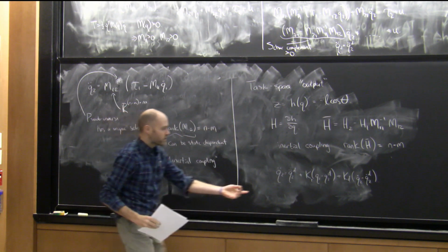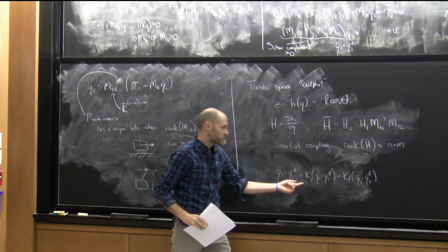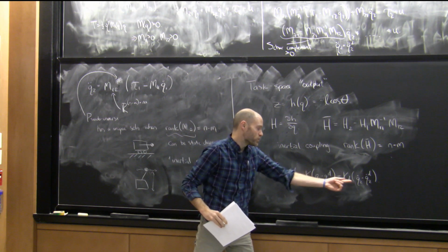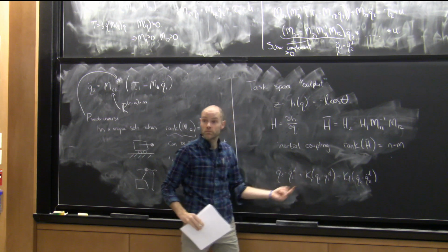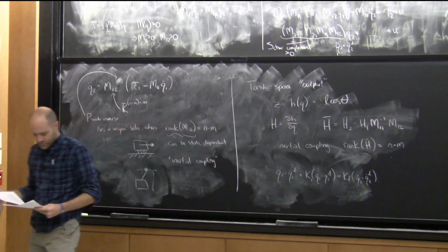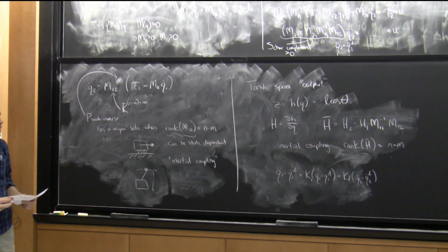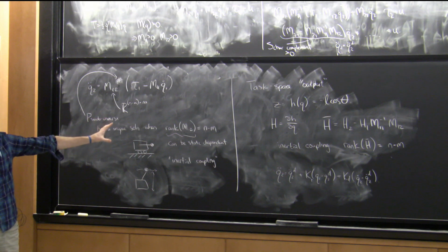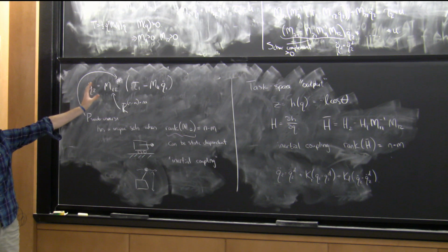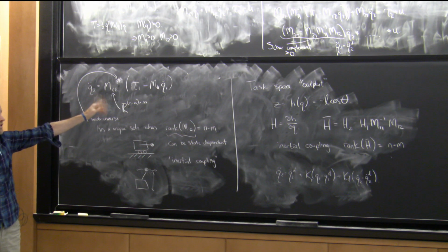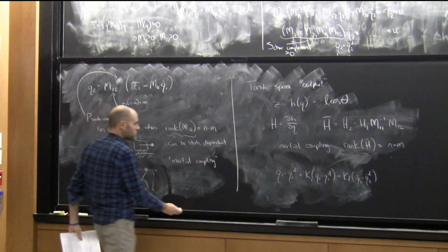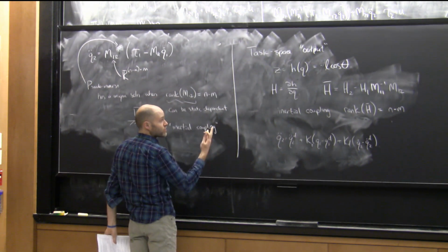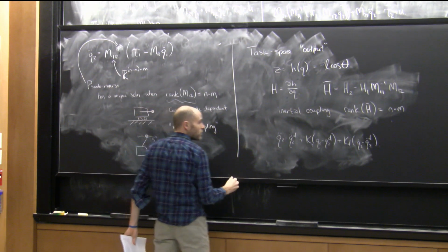Right, you could put in some sort of regularization there to try to feedback linearize that better. Okay. So we saw this in the specific symbols of the cart pole last time, but it's a general idea. You have M actuators, you get to control M things, as long as the inertial coupling in its general form holds.